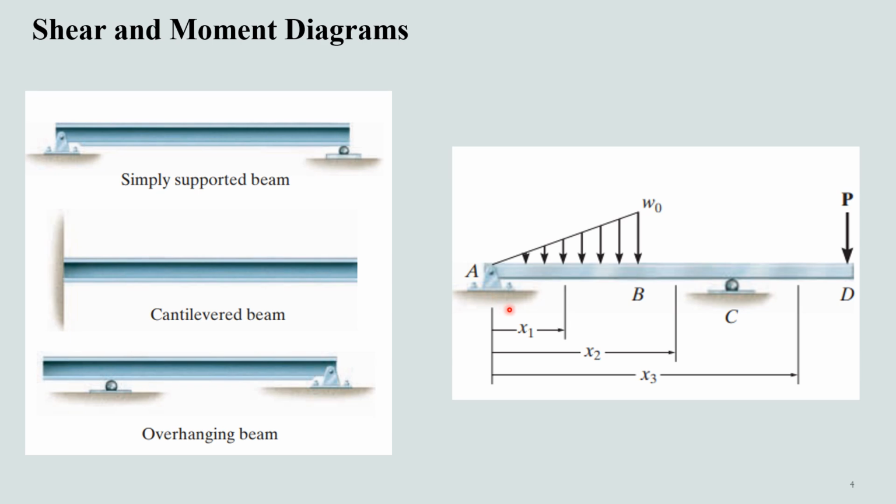We have discussed what a beam is and what is the purpose of the beam in different structural compositions. Now we can discuss the mechanics of the beam. Because of the applied loadings, beams develop an internal shear force and bending moment that in general vary from point to point along the axis of the beam. In order to properly design a beam, it therefore becomes necessary to determine the maximum shear and moment in the beam.